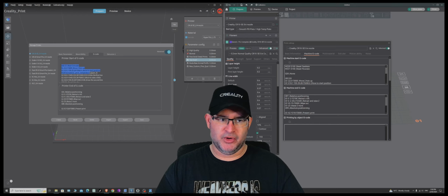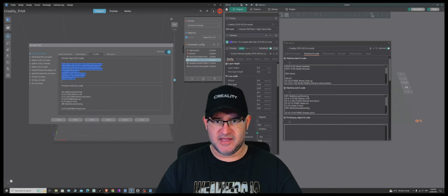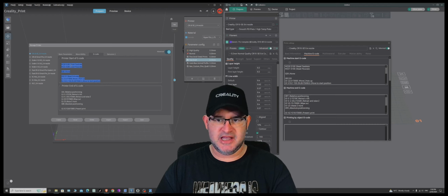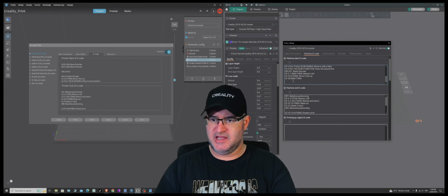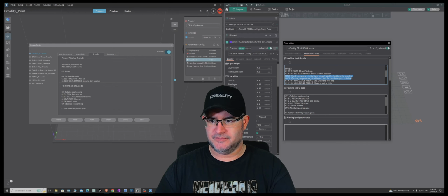Now, Creality Print doesn't let you copy; right click, nothing happens. So the easiest way to do that is to hit Control C and then come across to this point under here, left click and hit Control V. I won't do that just yet because this G-code's been modified in Orca Slicer. Now what's been modified? Nothing really that major. The difference is right here.